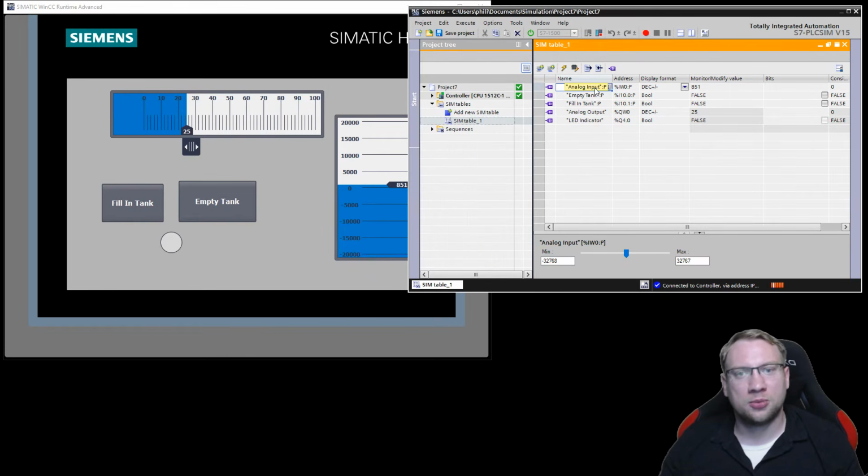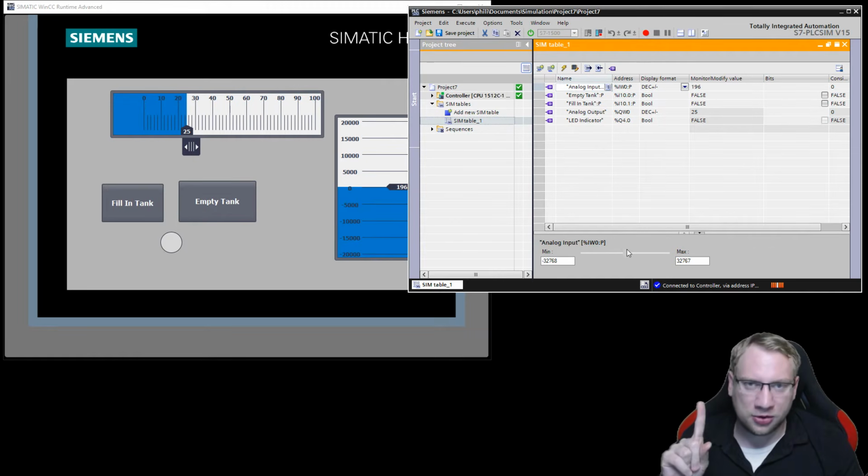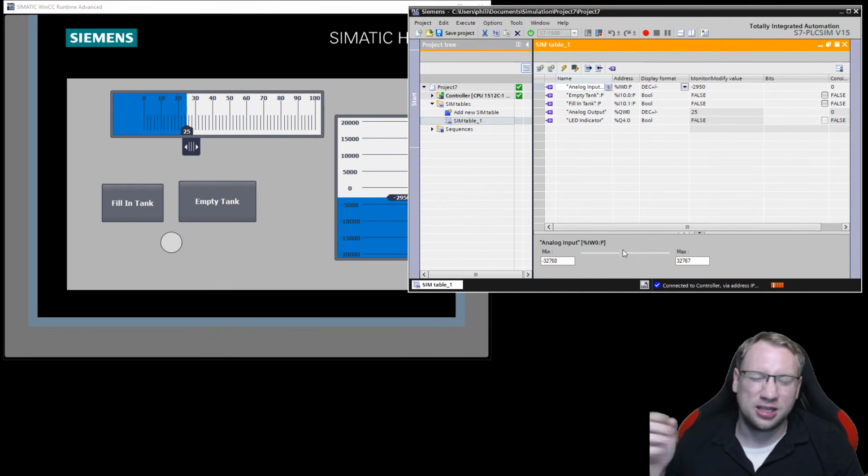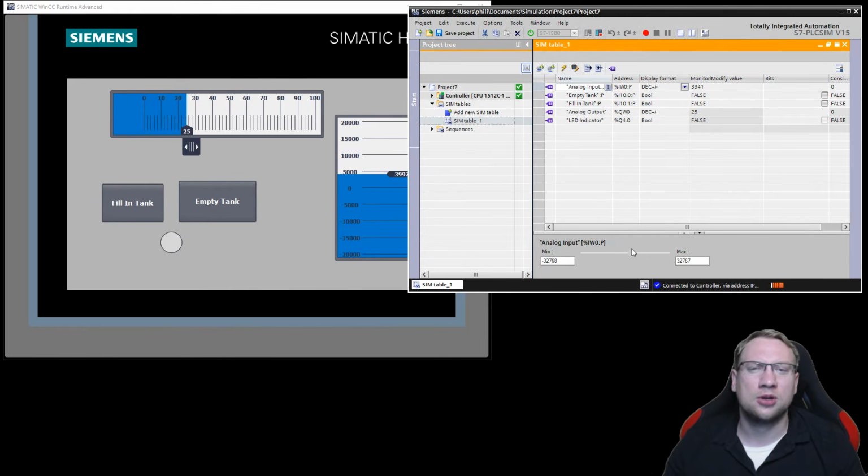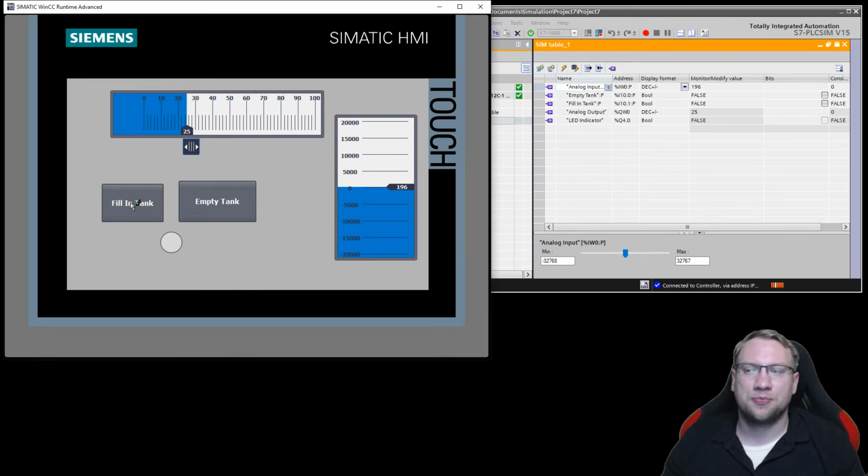Then I have my input, which I have to control from the PLC because it's in PLC input, right? And you see this changes, whoop-de-doo, whoop-de-doo. And you see the communication is a little bit slow, every 100 milliseconds. That's how we have the communication, every 100 milliseconds, not every millisecond or so. So it looks a little bit slow. That's what we've got.